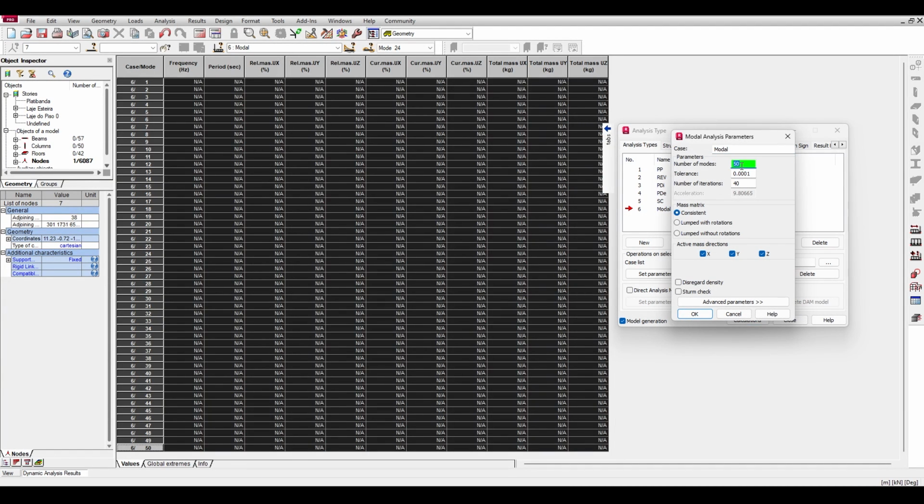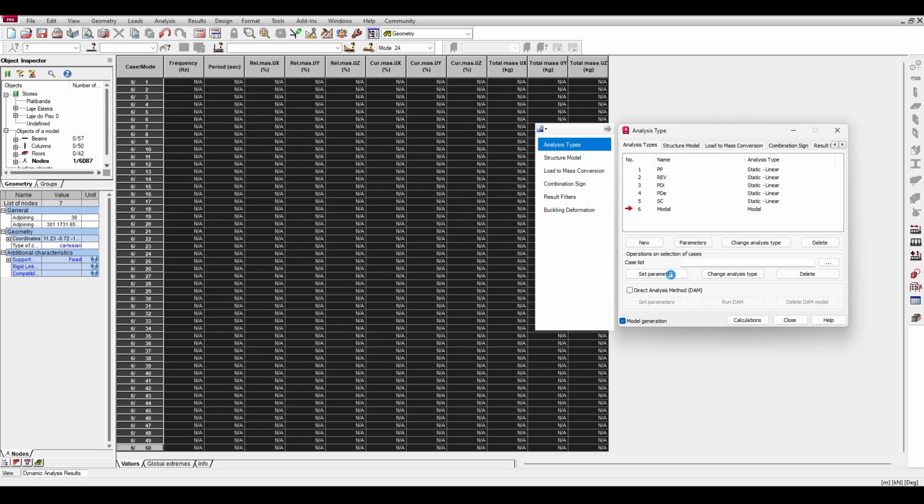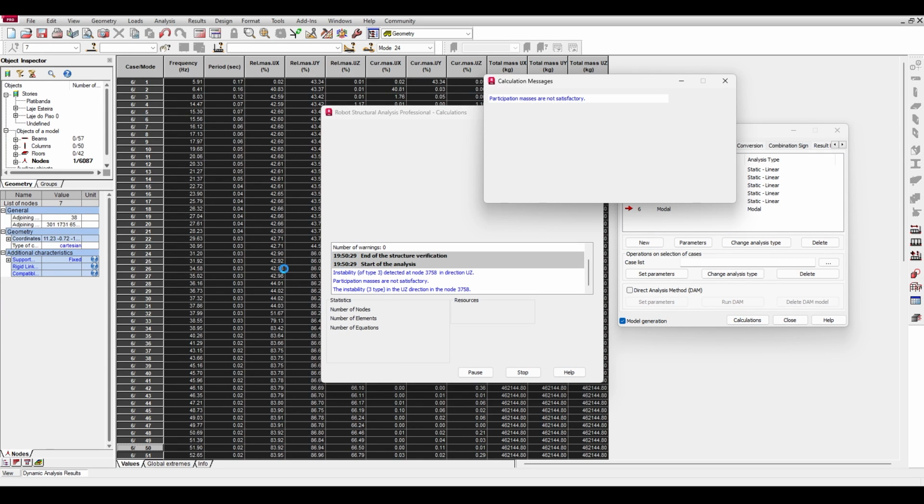I have a lot to say at the end of this video, but for now, let me just try to achieve the 85%. Now, by the way, it's warning me because I have the warning here running. I will just click OK here and I'll try it again. So now we are at 100. Okay, the participation of masses is still not enough, but I think I will stop.